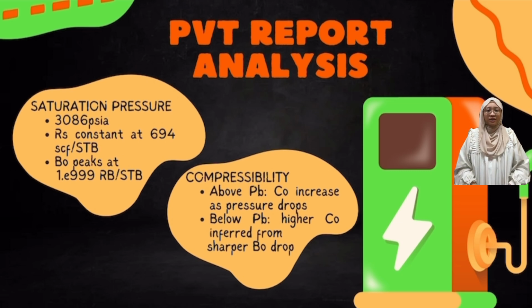For compressibility analysis, oil compressibility (CO) indicates how sensitive the oil volume is to pressure changes. In the report, CO is provided for pressure above the bubble point. For instance, at 7000 psia, CO is 1.1 × 10^-5 psi^-1 and increases gradually as pressure approaches the bubble point. This trend, increasing compressibility as pressure decreases, is typical and expected.